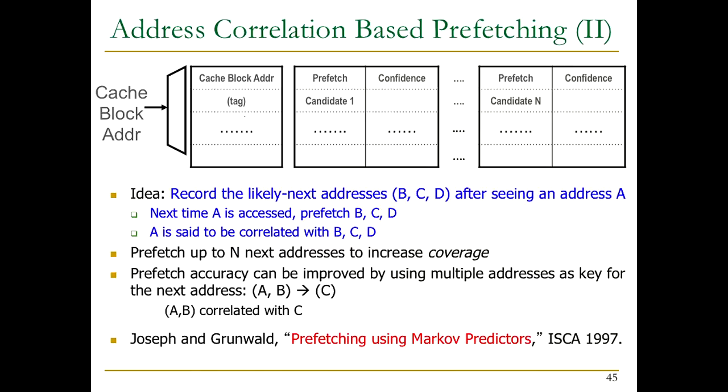Yes? Isn't this something like a trace cache? Mm-hmm. Yeah, in a sense, I mean, it has similarities, but the trace cache is very particular for instructions. But it does have similarities. It's like an address trace for data. You're right. So in that sense, it's similar, because the addresses that you keep accessing are repeated. Yes. But we're not storing the data over here.